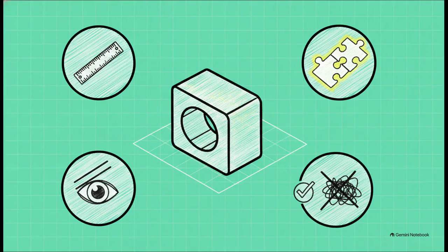We really have to establish the absolute necessity of a standardized language across all fields, from mechanical to civil engineering. Without these standard rules, chaos would completely reign on the production floor. The standard dictates that this visual language applies across the board. A drawing must define a part completely, no guessing allowed, ever. It uses one uniform unit throughout the entire drawing, often millimeters, entirely without writing the unit symbol.